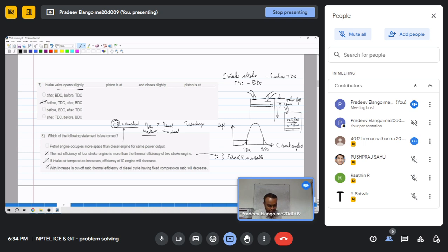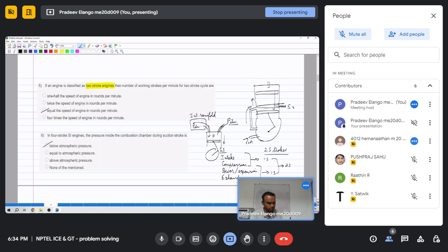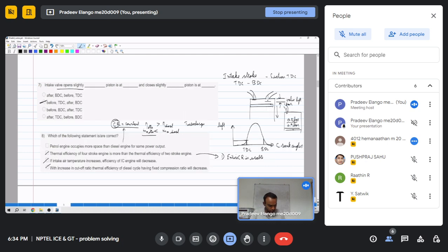That means in case of 2-stroke engine, we saw say 20% or 30% of the stroke of this piston is not used for compression. Only beyond the transfer port you use for compression. So this will lead to lesser thermal efficiency. Okay, so the entire compression ratio is usable for 4-stroke engine.